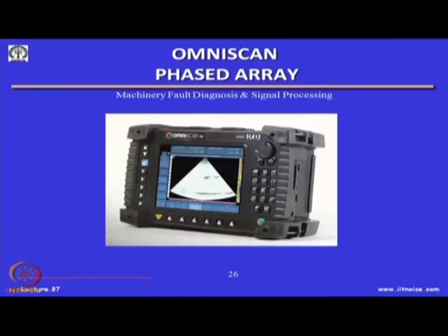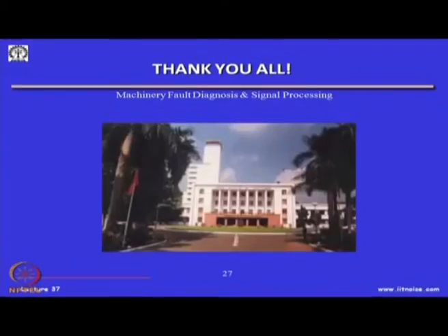This is one such phased array system which we have in our laboratory, wherein you can get an image of the area where you are scanning, and this is very similar to the doctor's ultrasound sonogram which you would have seen. So, we can see a defect here in the C scan. Ultrasound has become very popular because of the software which is available and because of the advantage in phased array electronic systems, which can be used for doing a quick scanning of systems and finding out defects. Thank you.